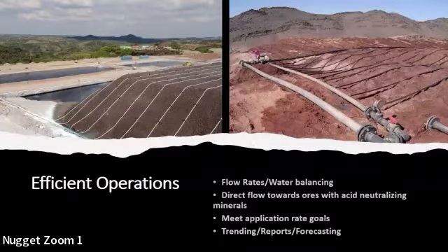This was to calibrate the stratigraphic interpretation that was obtained, and the samples were included for the USCS classification, to calibrate the interpretation against what was expected from the operation, in terms of what the operators were aware of, where the points of most concern were, with higher potential of failure or more likelihood of being liquefied, in terms of static or dynamic liquefaction.